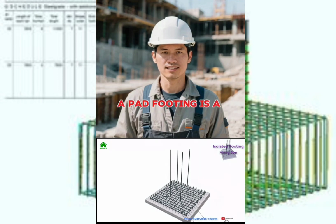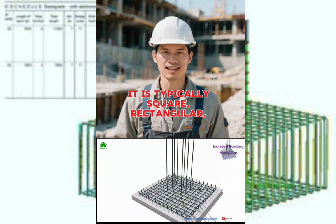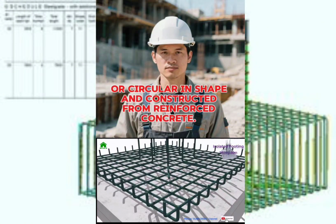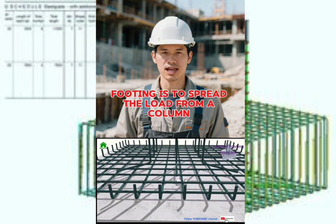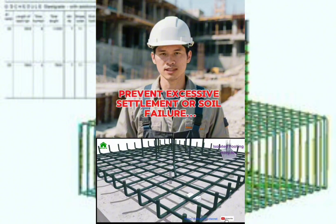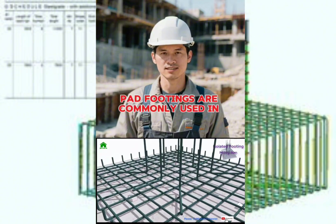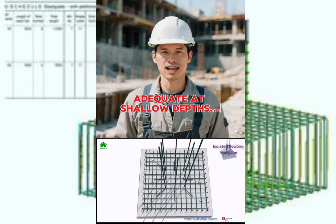A pad footing is a shallow foundation that supports a single column or a small group of closely spaced columns. It is typically square, rectangular, or circular in shape and constructed from reinforced concrete. The primary function of a pad footing is to spread the load from a column over a sufficient area of soil to prevent excessive settlement or soil failure. Pad footings are commonly used in low-rise and medium-rise buildings, where the soil-bearing capacity is adequate at shallow depths.